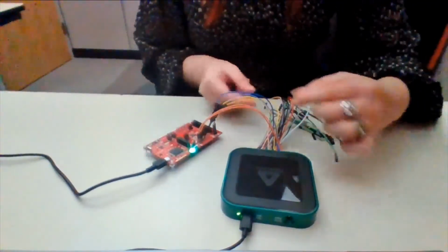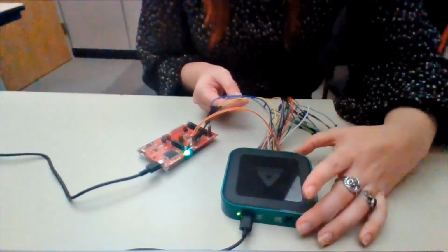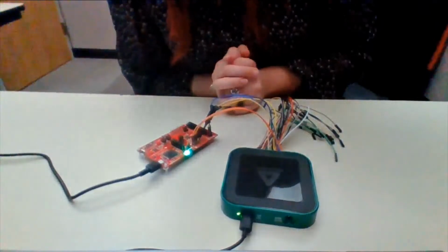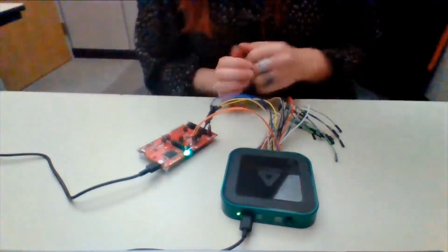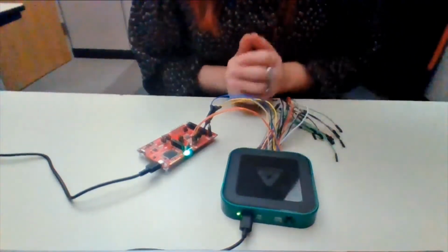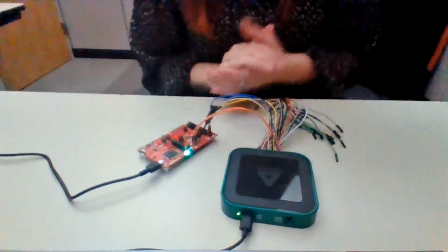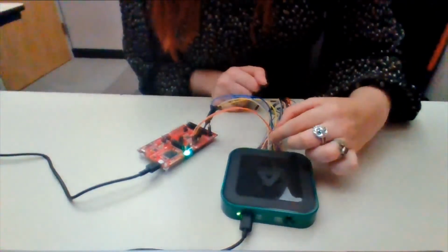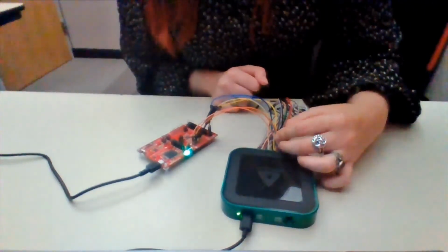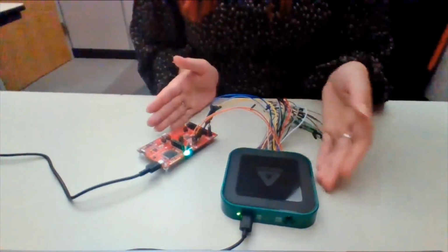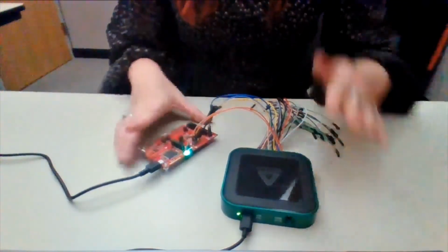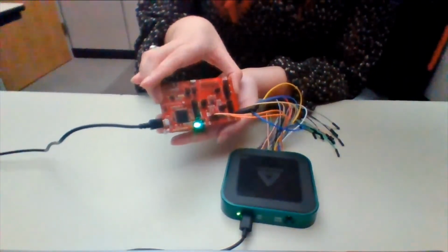As you can see here, the yellow wire is connected to the waveform 1 from the logic analyzer, helping to provide the input onto pin PA18. And then we also have the blue wire also connected to that same waveform to help measure it on the scope as well, so we can get a visual view. Then we also have the orange wire here, which is connected to PA16, which is reading the output of the op amp in the programmable gain amplifier demo. And once again, here is the MSPM0L1306 launchpad and the setup that we have.